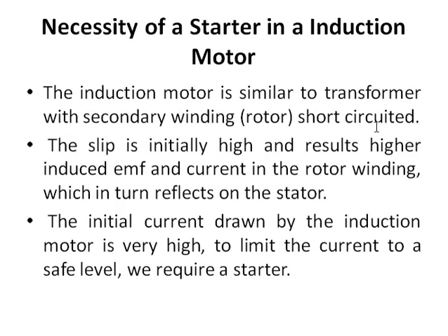This is very similar to a transformer, where the stator is similar to the primary winding. A supply is given, it creates a magnetic field, and that gets associated with a secondary winding, that is the rotor winding. The only difference here is that in an induction motor, the secondary winding or the rotor winding is short circuited. The slip is initially high and results in a higher induced EMF and current in the rotor winding, which in turn reflects on the stator.